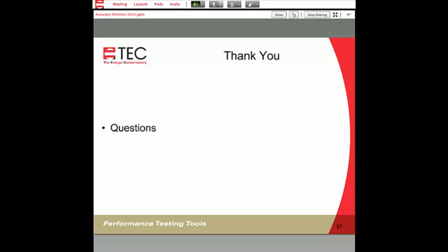Question, a little bit different question. Why does the baseline clear when switching mode, as in from pressure flow to pressure flow at 50? We did that primarily as a safeguard because we're not sure who's using it and what they're trying to do. So to be on the safe side, we just had the gauge clear the baseline and start over. We know it's a little bit of an inconvenience, but we hope that it actually helps you with providing more accurate readings.